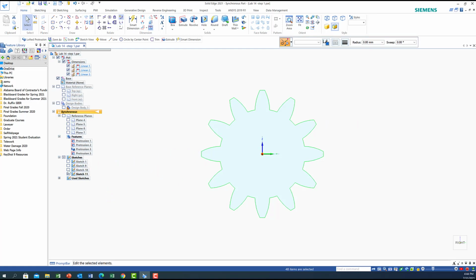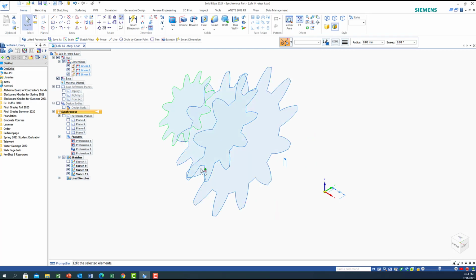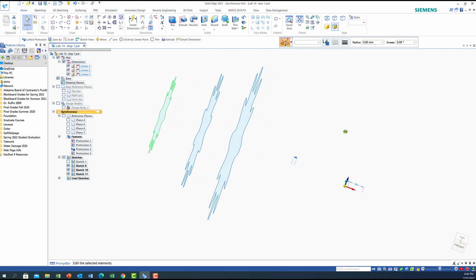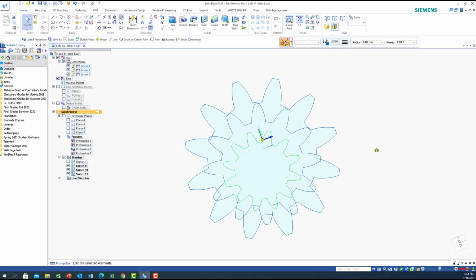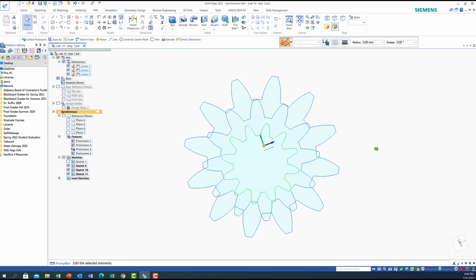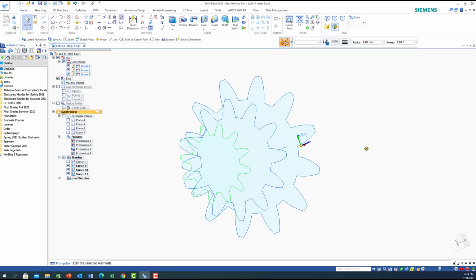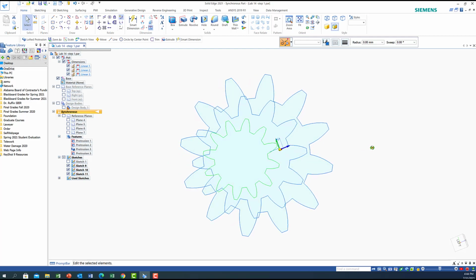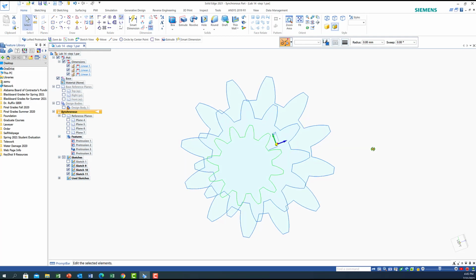So now we need to connect all the shapes. So what I'm going to do is just go home, and I'm going to highlight all the last 3 sketches. Okay. Now I want to connect them. So how are we going to connect them? So now we're going to say loft.